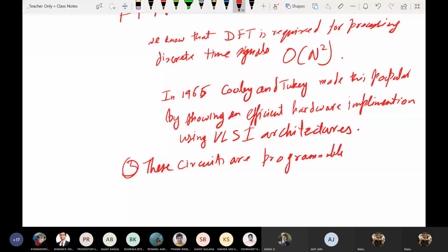You tell me that, okay, I want a diode detector, which involves a rectifier followed by a low pass filter. I say, okay, give me the samples of the analog signal. I take the digitized version of that analog signal, chop off all the negative parts, that gives me the rectifier, and then simply low pass filter it.